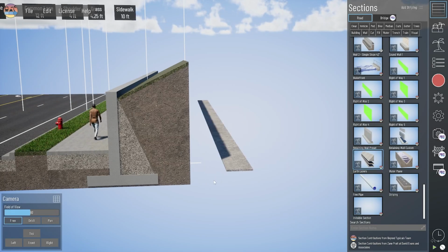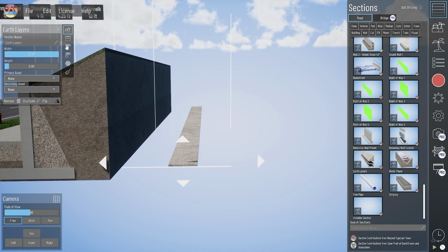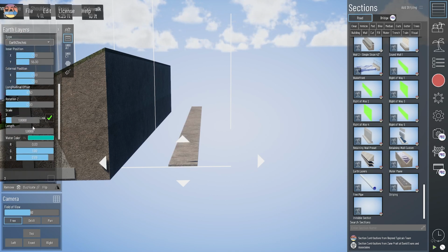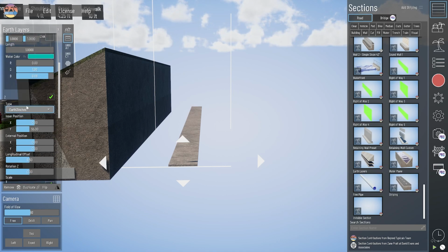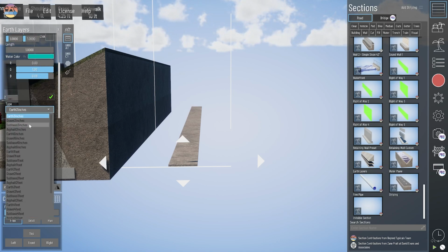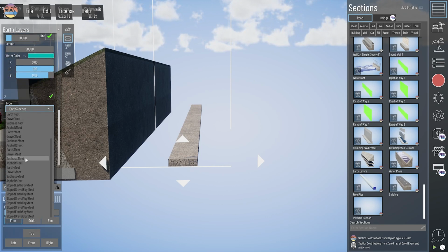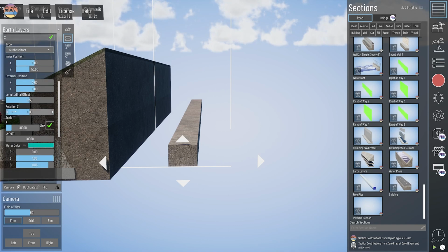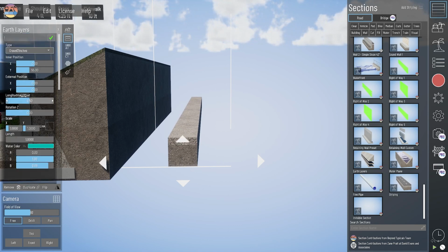One other note on these earth layers, as I alluded to earlier, I'll widen this out so we can see this a little better. There are 3 different layers we can toggle on. So you'll see we've got 1, 2, and 3. So we can show maybe some gravel and some subbase. Let's make the subbase a foot, and then earth we'll do 3 feet. And we can adjust the positions on these in the Y direction to show those over the top of the other.